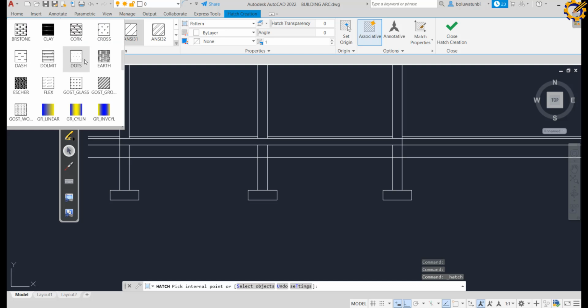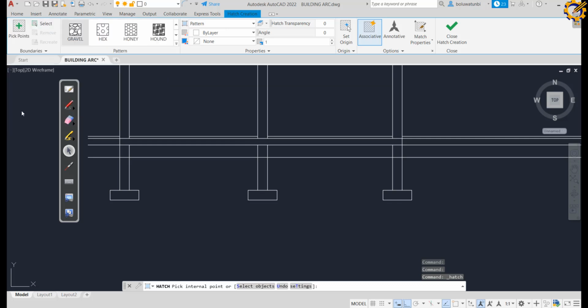You remember the use of symbol I explained when drawing. So since this is an architectural course, I can actually make use of stone for my hardcore. But if you become a teacher and you are teaching technical drawing in school, you don't use stone. You use that symbol I showed during the last video. That symbol is acceptable both in architectural drawing and technical drawing. But the one I'm going to use now is only acceptable in architectural drawing. So I'm going to use this gravel.